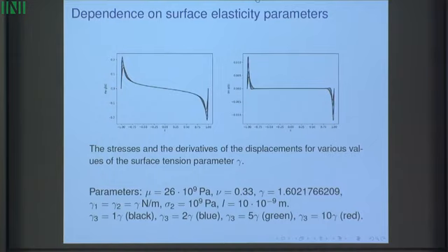And again, the classical solution near the crack tips is singular. So hence, here are these jumps, but in this particular model, we can tie them back up. Now, if your surface energy parameters are very small, of course, your system tries to go to a classical state, and that leads to numerical difficulties with solving your system, because we have very tiny coefficients, and the solution is just not very accurate. But if it's in a moderate range, then the solution is fairly good.